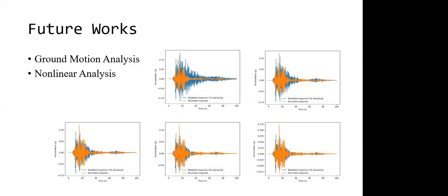So what kind of changes are you planning to do to your existing model? Like you are going to change the elastic elements to fiber sections. Apart from that, are you planning to do any other changes? I'm just changing some elastic to fiber, I haven't decided yet, so it's going to be nonlinear, and I'm going to make the hinge at the top and the bottom of the column, to simulate the damage. Okay. And you'll be running uniform excitation, right? Yeah, at this point of time, it's uniform excitation.